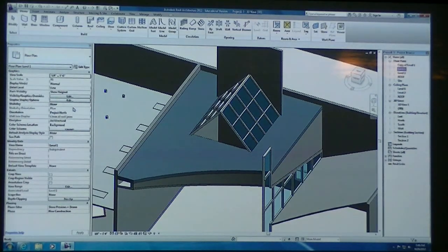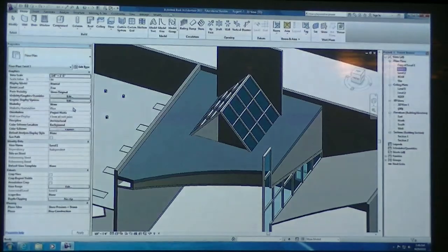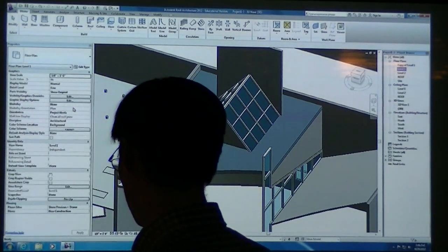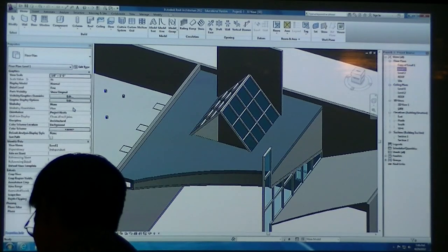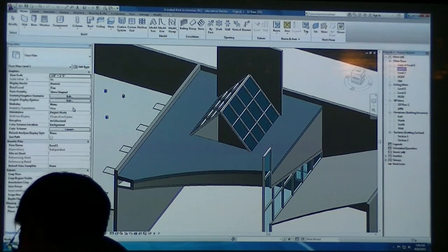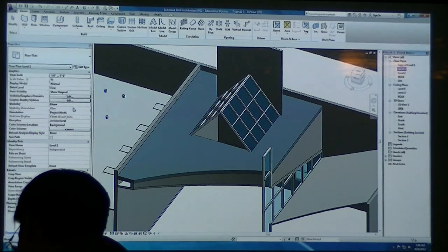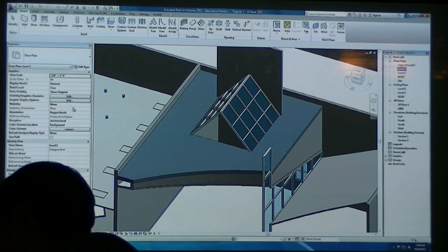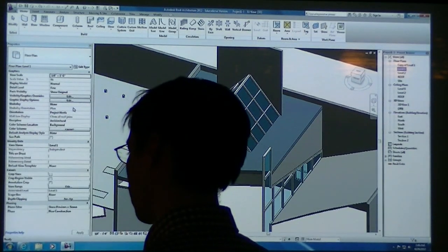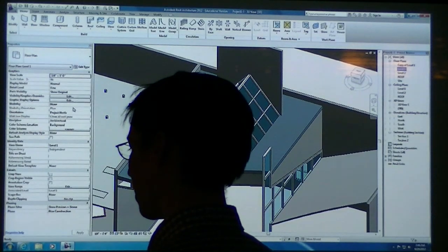But what you can do is model this line in the stair sketch, and you can actually make it turn onto the floor and just make sure it's not posted to the stair, and it should kind of automatically join.